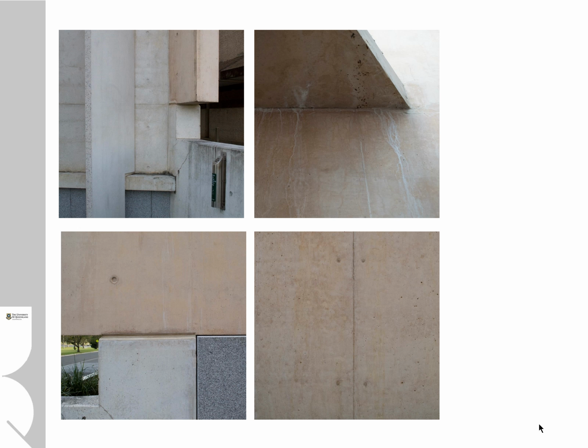Now, because the two had to be cast separately, the formwork joined between them, and because there's no rebate or anything around there, it has meant the necessity for an extremely tight join there, which is almost impossible for such a sharp angle.